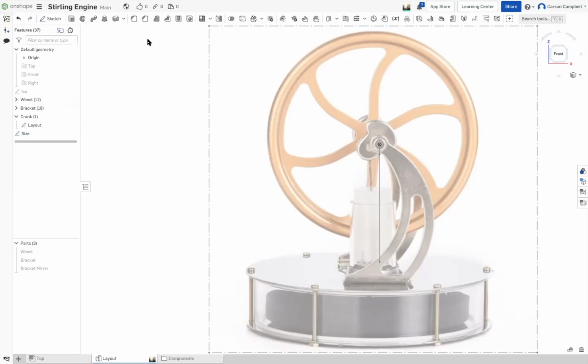If we buy this from Misumi, we can buy a precision shaft, and we can also have them thread the ends so we can use bolts to bolt this all together. I think that's beyond the scope of what we're doing right now, but that's basically where you start to make your decisions. I always like dealing with nominals.